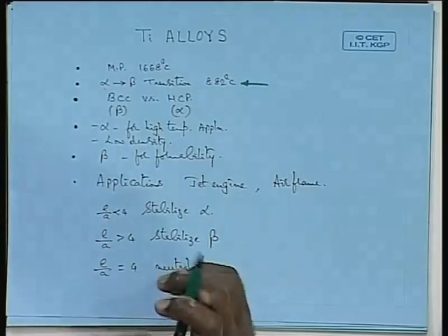So once you have an allotropic transition, there is a lot of advantage, and that's the basic advantage of steels. Why steels have become so popular among all the alloys is just because of these allotropic transitions. The moment you have an allotropic transition, you can heat treat it. If you don't have an allotropic transition, aluminum, pure copper, you cannot do any heat treatment. So the strengthening is limited in metals without any allotropic transition. Aluminum can be strengthened only by putting some precipitates into it. You can do some what is called solid solution strengthening.